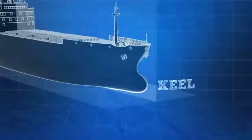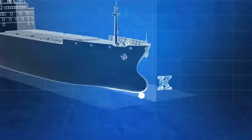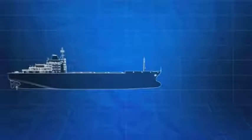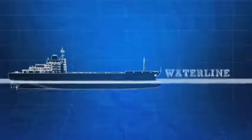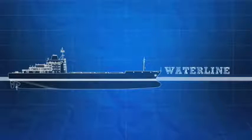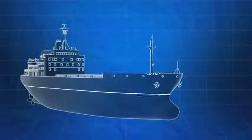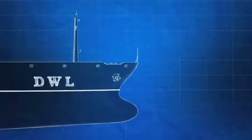The lowest point of the keel, or K, is the point from which vertical distances are measured on a ship. K is located at the intersection of the center line and the baseline. The water line is the intersection of the surface of the water a ship is floating in with the sides of the ship's hull. When a ship is designed, the naval architect determines the design waterline, or DWL, that represents the waterline of a ship under full load or maximum draft conditions on an even keel.